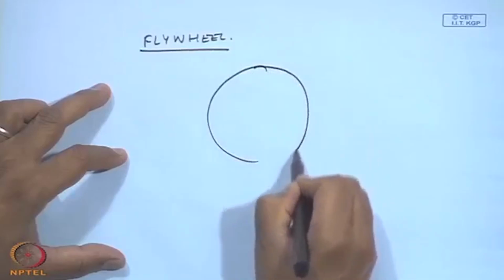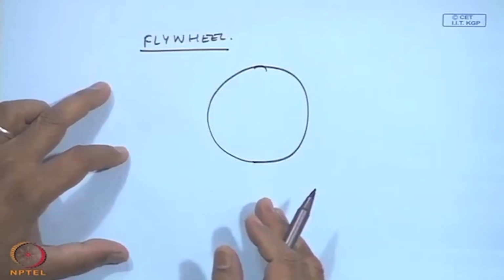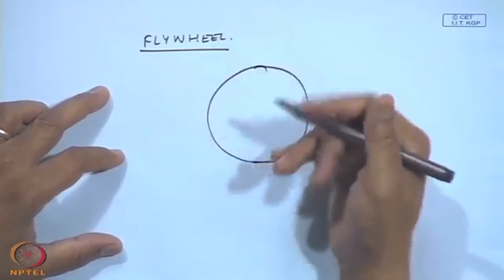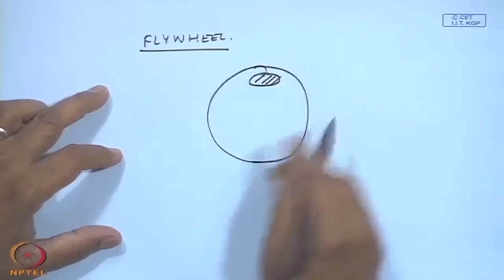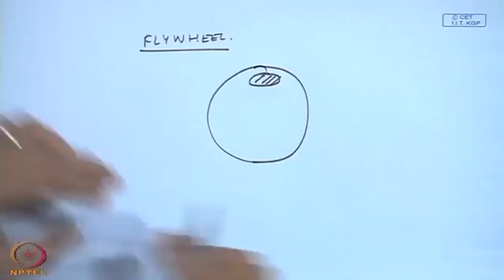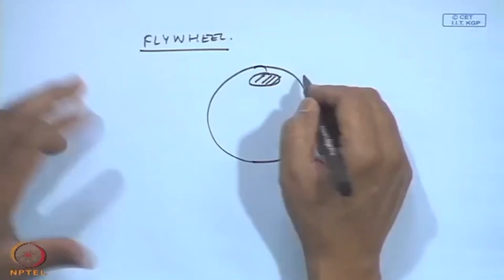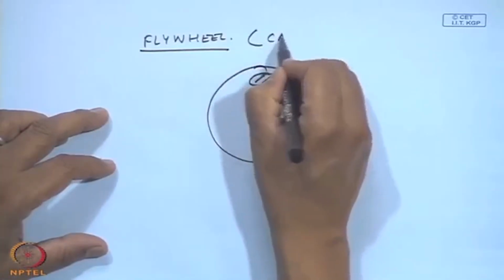Of course, if you have a larger number of cylinders, the cycles are balanced, and then the flywheel will be of a lesser size. But I am talking about single, 4-cylinder and 3-cylinder engines, wherein the flywheel is mounted after the clutch, after the crankshaft, so that we reduce the cyclic engine variations. And imagine such a flywheel has an amount of unbalanced mass. This is going to give an unbalanced force onto the shaft, and this is not desirable, and usually flywheels are casted.